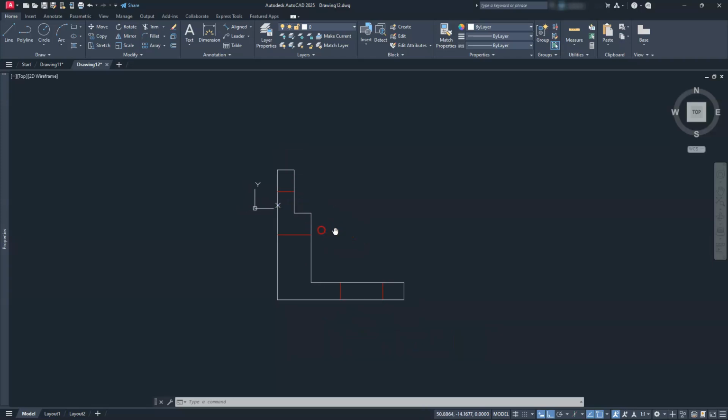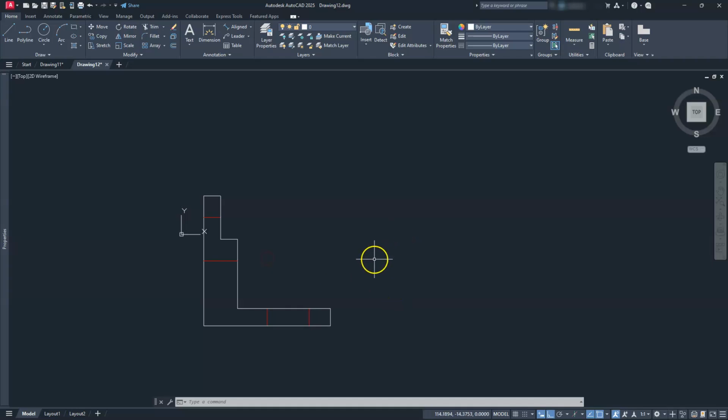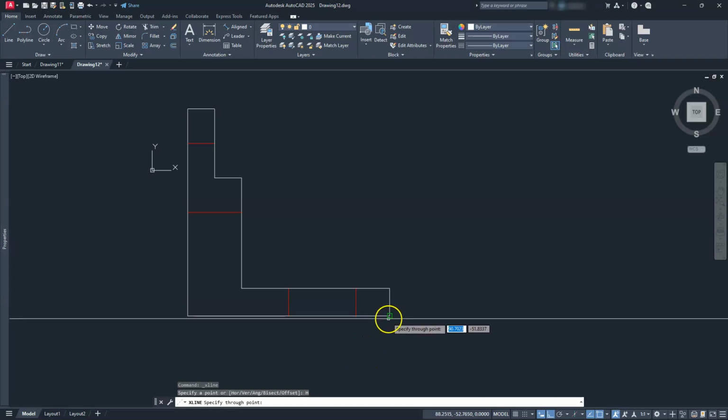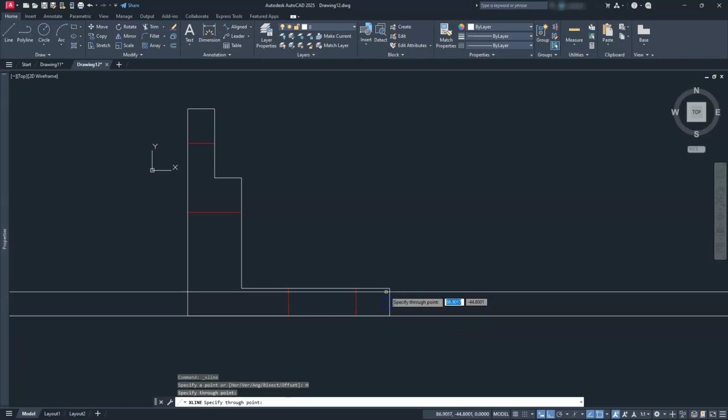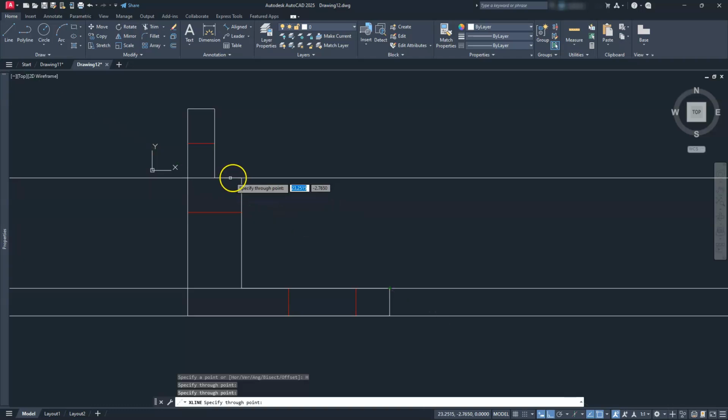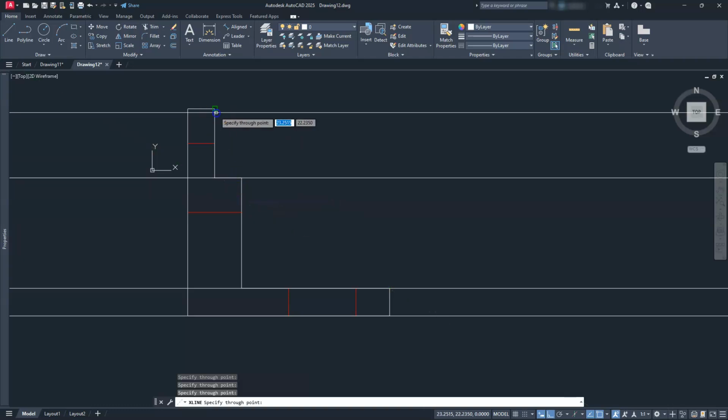Let's go ahead and create the right side view of this one. So remember that anytime you're creating views, these have to be in line with each other. So the first step I'm going to do is use this construction line method here. Make the lines horizontal. I'm going to click on all of these endpoints, right? So give it a second here. I don't know why my computer is running a little bit slow, but here we go. So I'm just going to select these endpoints. And we have one more here.